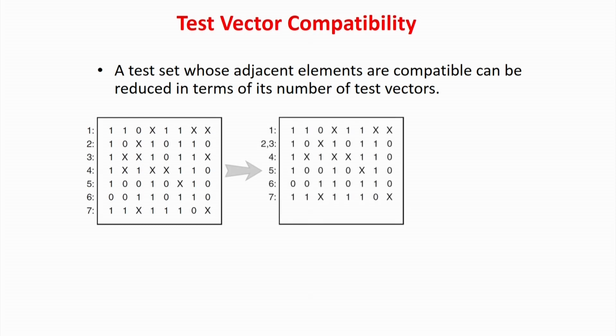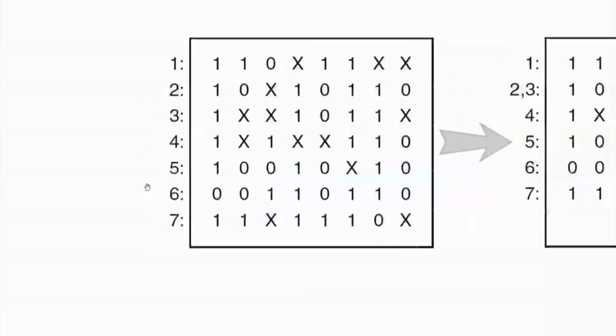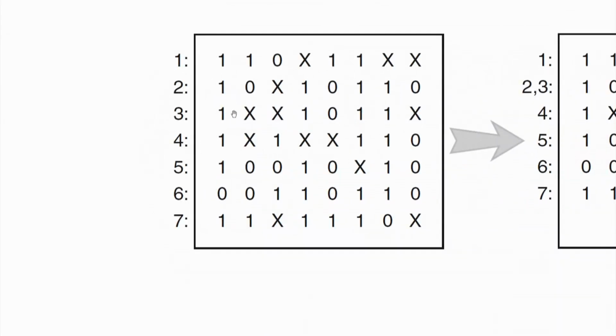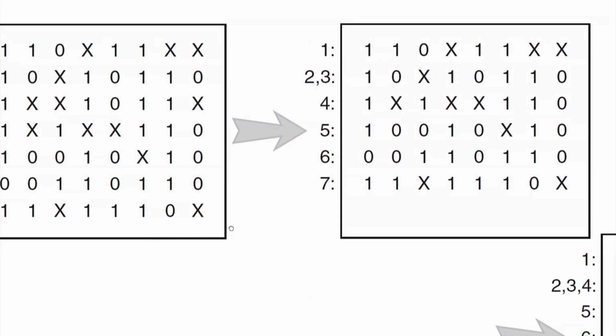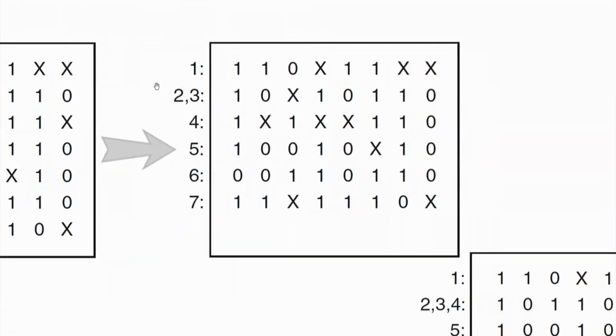Now, there are some ideas I will tell you. Say for example these are the test patterns which have been generated. There are some test patterns which are generated and somebody has sequenced them. You can easily see that 2 and 3 are compatible, because 1 1 0 x x and x 1 1 0 0 1 1 0 x are compatible with each other, so you can retain 2 and merge 3. That is what they have done. So I have compacted 2 3 in this manner.